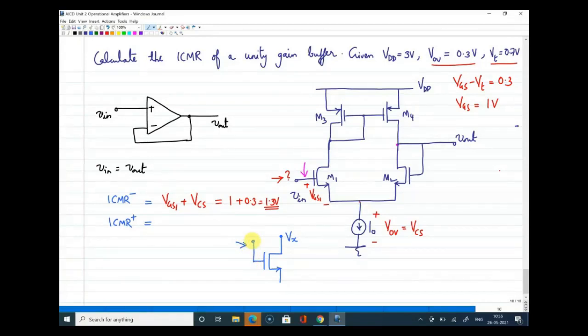Yes, Bhavya. Yeah, a lot of answers are there. Right. So the answer is your gate voltage can go maximum of one threshold higher than the drain. That is our condition for saturation, right? Condition for saturation is VD should be equal to VG minus VT. So the gate voltage can go maximum up to one threshold higher than drain. That is a very simple logic behind this.